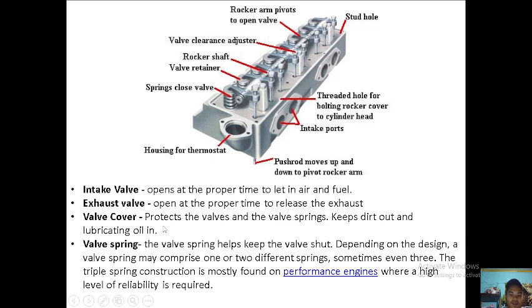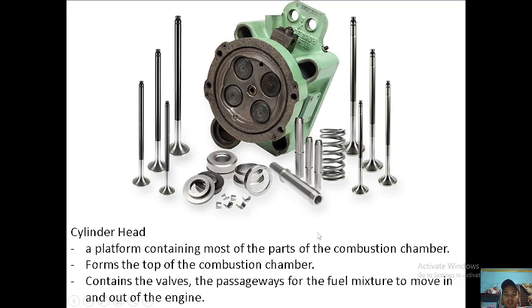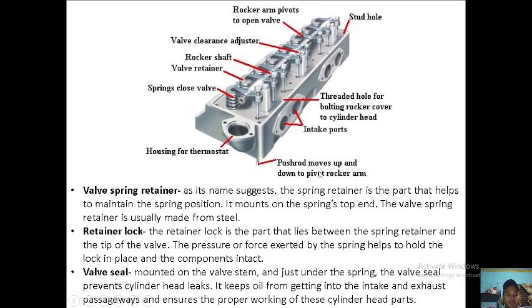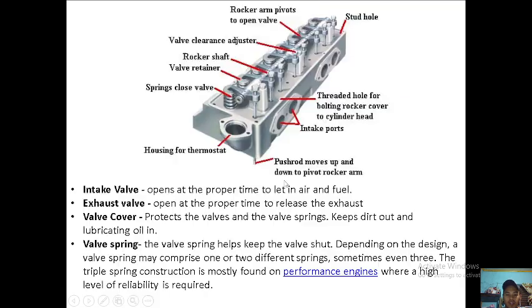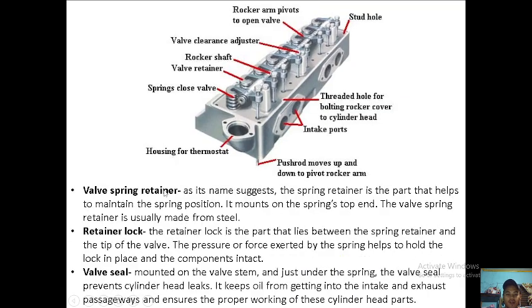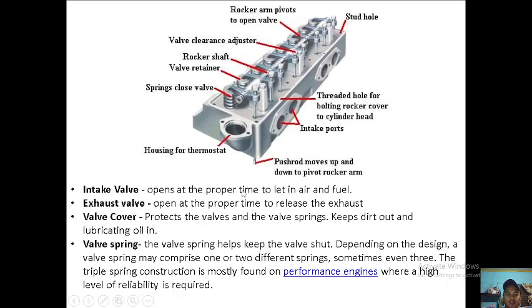We have the valve cover that protects the valve, keeps dirt out and lubricating oil in. We have the valve spring, this one. The valve spring helps keep the valve shut. Depending on the design, a valve spring may comprise 1 or 2 different springs. So this is the valve spring or retainer spring, valve spring, and we have the valve spring retainer.